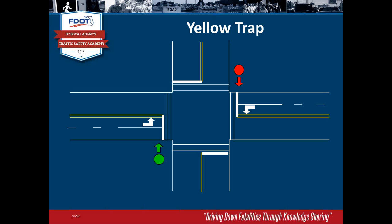And now let's say our eastbound lefts are gapping out and about to end. So they show the yellow for that, and then we go to the permitted phase. After we end the protected portion, now we're operating permitted.